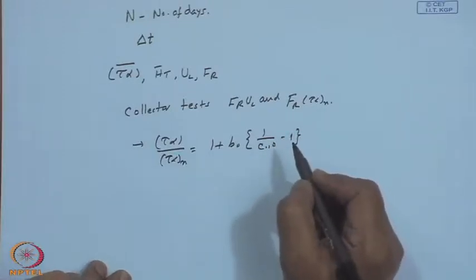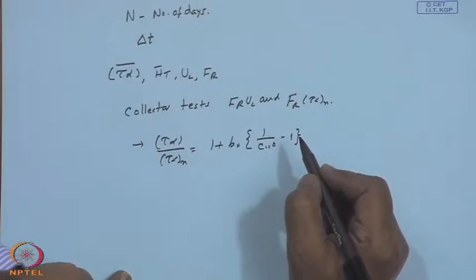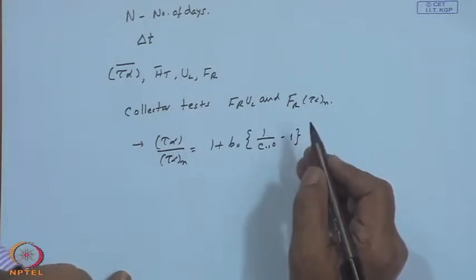And you have the effective angles of incidence for the direct radiation in the form of a graphical representation, or the effective angle of incidence for the ground reflected radiation and the sky diffuse radiation, which are constants, they do not change with time, they are a function of the slope beta only, that is your theta g and theta d. So, one can estimate your tau alpha bar as per the relations which we have already dealt with in detail.